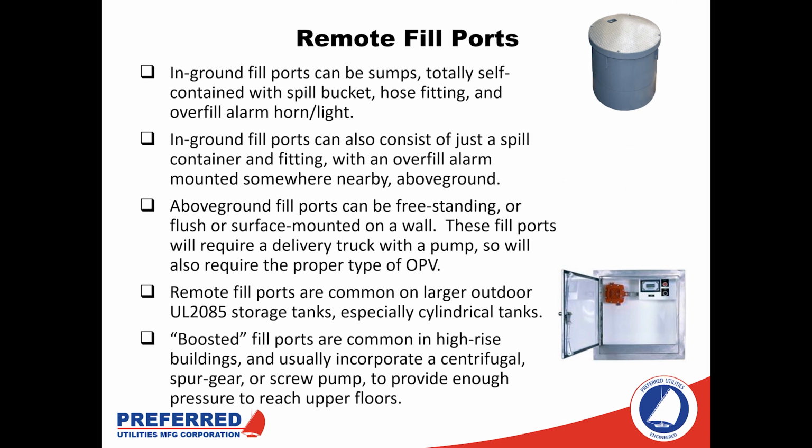Moving throughout the system, another critical part of the system is the remote fill port. This is the part of the system that the fuel oil delivery person is going to be interacting with. They're typically not going to have access to the main tank itself or to the other controls. So this is the part of the system that's going to indicate to them any sort of alarm conditions, like high level in the bulk storage tank, that they're going to need to know about.